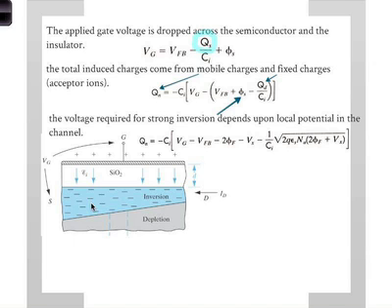That's where the junctions are. And if the local potential across the inversion layer changes, you expect that depletion region to change. It's very similar to the JFET situation we had. Yes? So basically for equation 6.32, they use phi F specifically because it's at the source. Non-bending. Yes, exactly. It's at one location.